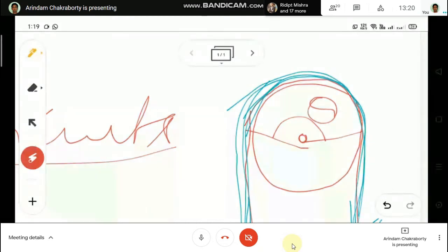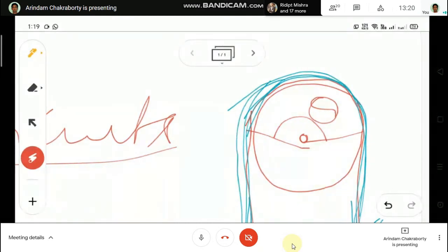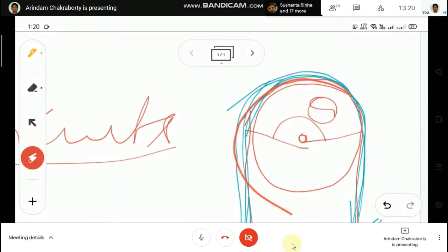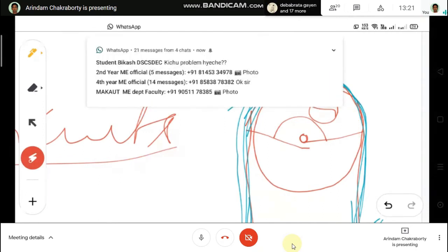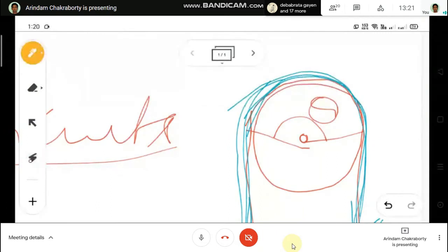So let us get to the point. Since the pulley transfers motion to the belt, or in the other way, the belt transfers motion to the pulley, vice versa, the motion is transferred through the contact angle, that means the contact area. So there will be a friction coefficient mu. Fine.